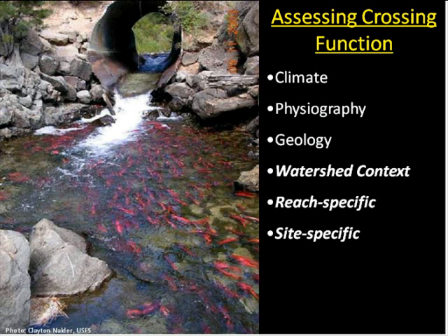Again, using a geomorphic approach will allow you to assess passage condition without a detailed knowledge of individual stream organisms, their mobility, or migratory habits. Quantifying the departure of a stream from its natural state, in quotes, will help you describe the relative passability of a stream crossing and provide insight into designing for aquatic organism passage.